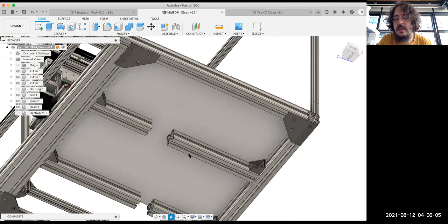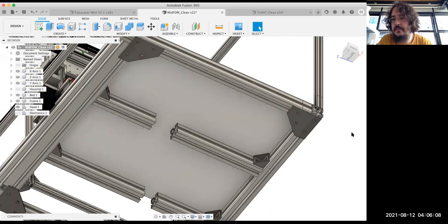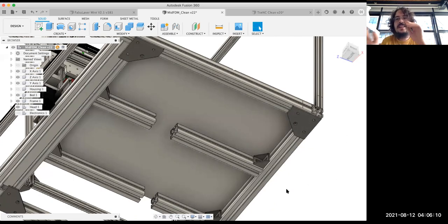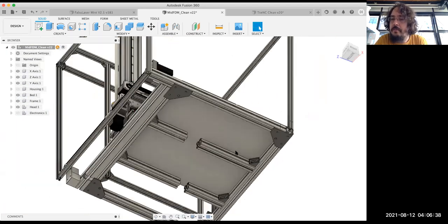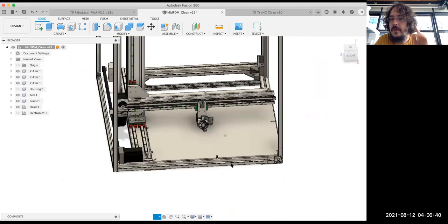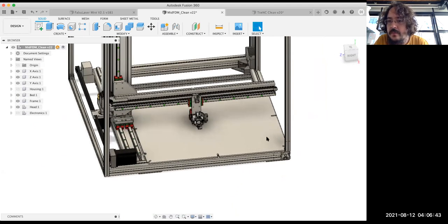They're not drawn now in this schema, but they are silicon heaters, AC heaters. I'm going to show you the AC heaters in the machine maybe. They are, for me, the best heaters because they heat very fast. They are cheap and very powerful, but they have a huge drawback, which is that they work at 250 volts. So you need to be careful because they are connected to your aluminum part, and the aluminum part is connected to everything, and the machine is also grounded. So if you have problems, you need to do the electrical insulation well. Do you have other questions? Okay, thank you.